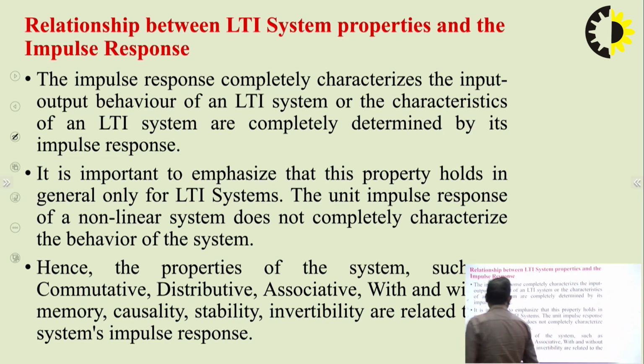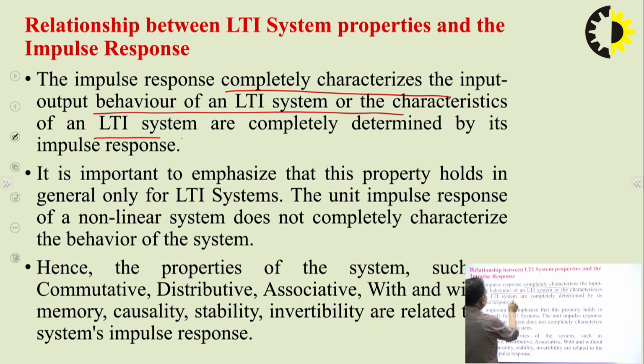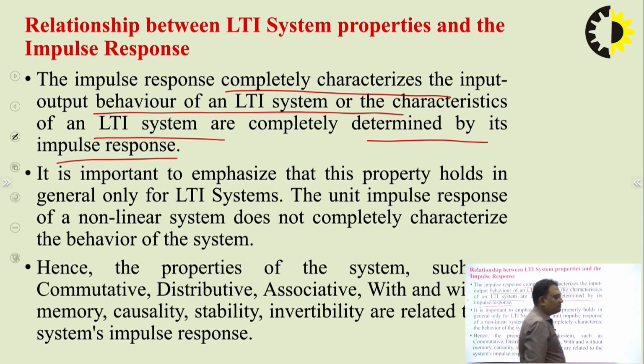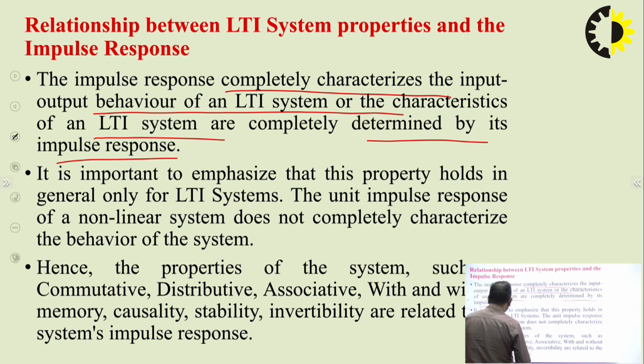the impulse response. So this impulse response completely characterizes the input-output behavior of an LTI system; the characteristics of an LTI system are completely determined by its impulse response. Means if we have the impulse response of a system, then we can define all its properties. The impulse response is itself complete information about a system's properties. It is important to emphasize that this property holds in general only for LTI systems. The unit impulse response of a non-linear system does not completely characterize the behavior of the system.